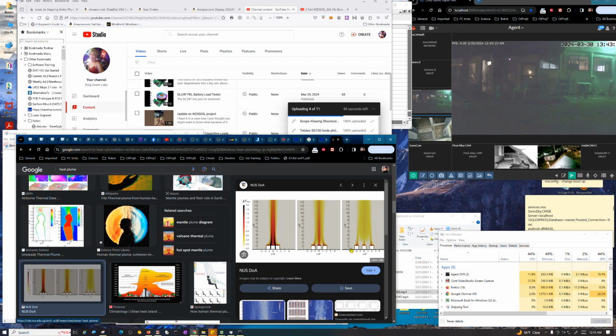Not so close though that your sensor's going to heat up due to radiative heating. Because if you're interested in the temperature of the air, it wouldn't even be a bad idea to temporarily put something that blocks it, like a piece of cardboard, just to take your temperature measurement. So you can catch the temperature of the air real quick and then remove it real quick, within a couple of seconds, however long it takes your thermometer to stabilize. Just to block the radiative, because you're really not interested in what the radiative heating is. You want to know the temperature of the actual air mass, because it's the air mass that's going to be drawn into the component and heat it.